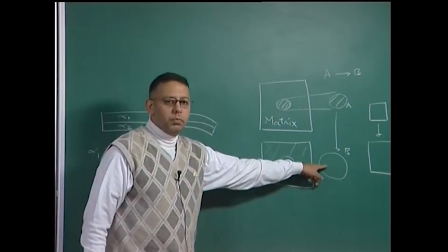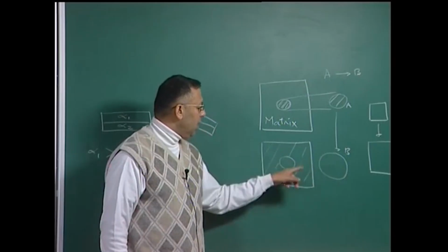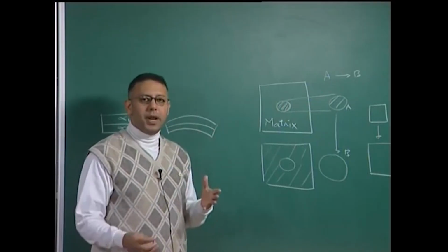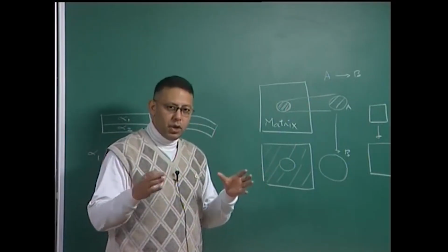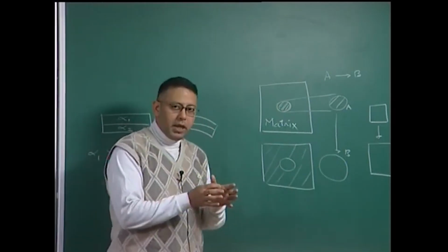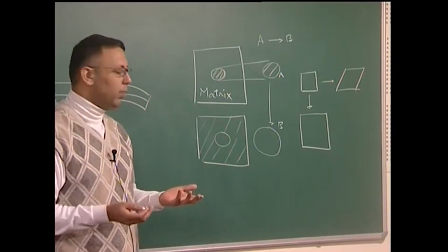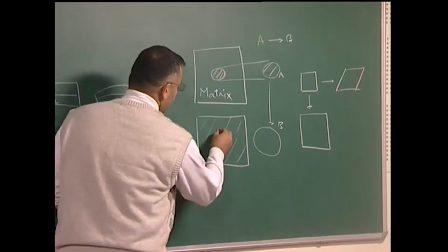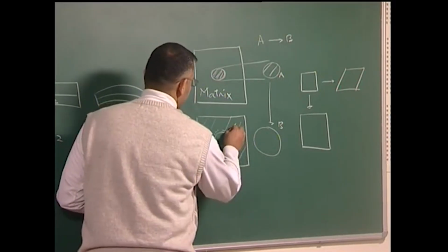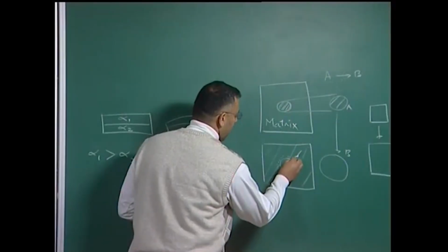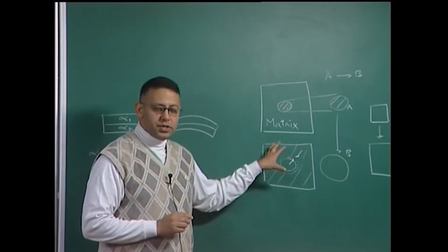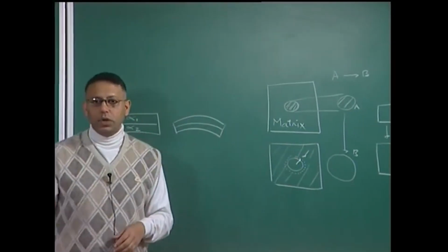In other words, this material B has to again fit into this hole from which it arose originally. This implies that the surrounding matrix will actually try to compress down this volume, because this now occupies a larger volume as in the example I have considered, and the material will want to expand outward, and this will come to an equilibrium configuration, wherein, I will just draw by dotted line the equilibrium configuration. The outer body is trying to push it inward, the inner expanded body wants to go outward, and finally, we have an equilibrium configuration. This leads to a residual stress state in the material, which is what I am showing you as the plot.